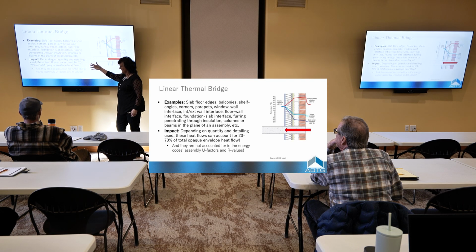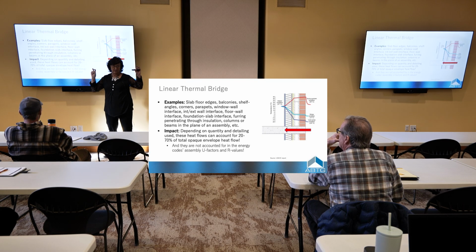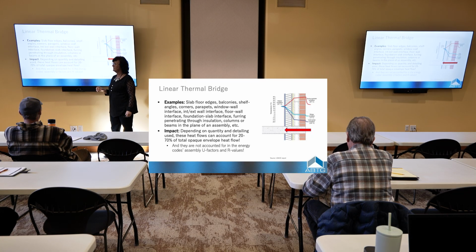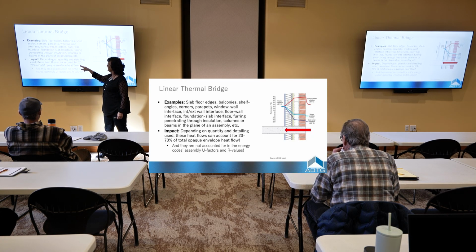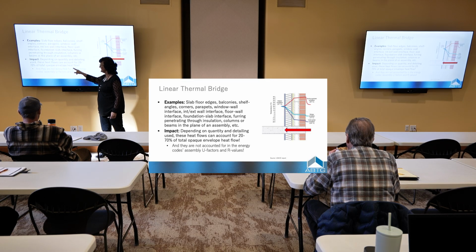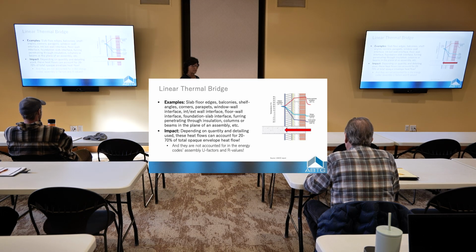I like this. This is in that thermal bridging details document on continuousinsulation.org. Depending on the quantity and detailing used, the heat flow can account for 20 to 70% of heat flow through the thermal envelope.